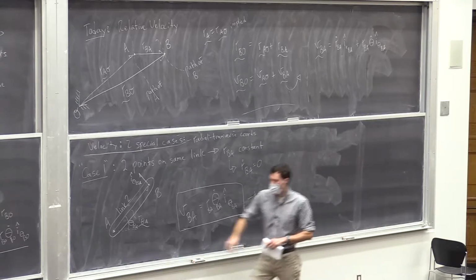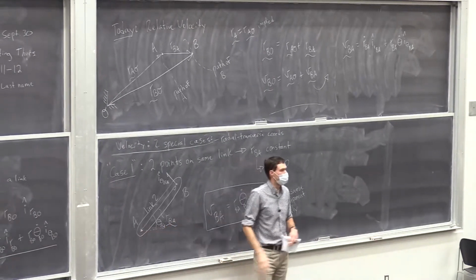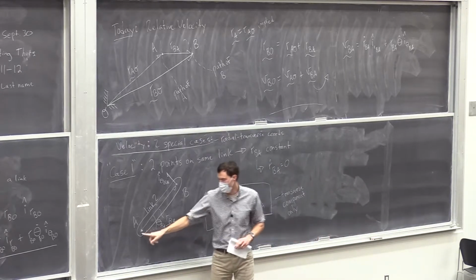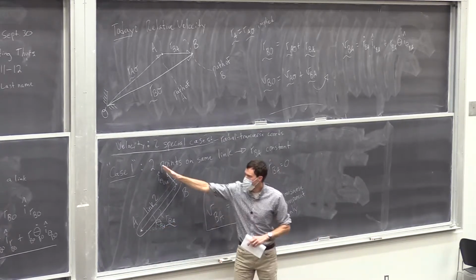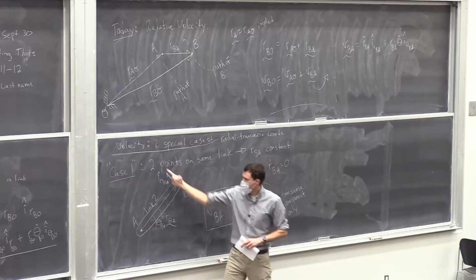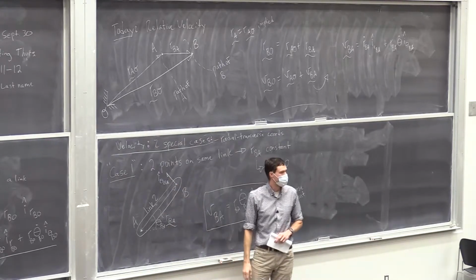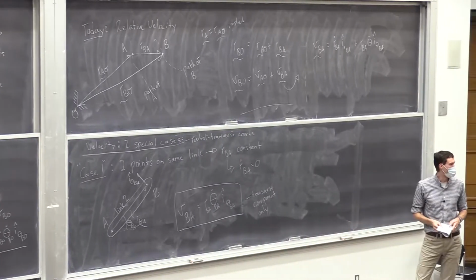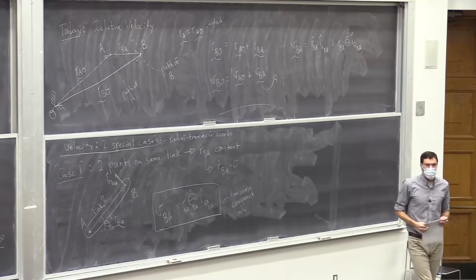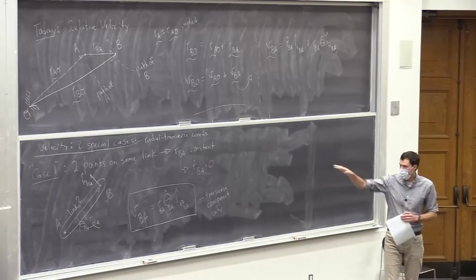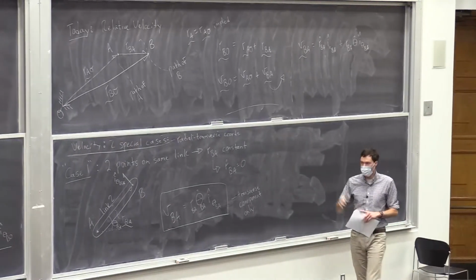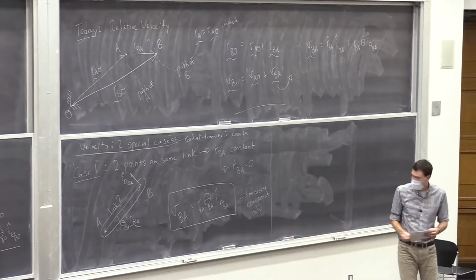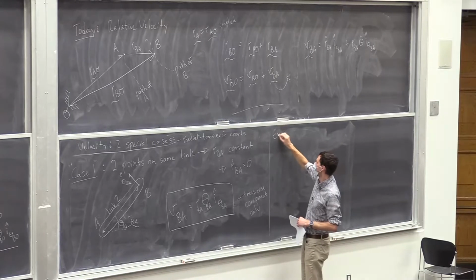Okay, and that should make sense. Imagine if A was not moving, like it was pivoting around the ground, a ground base pivot. B would be moving at this instant perpendicular to RBA. Okay, any questions about this? This is our case 1. It's pretty straightforward, and we're going to hunt for these in our mechanism analysis because they're really easy. Always transverse direction, really easy to just put them up on there. So I'm going to look at a quick example with you here.